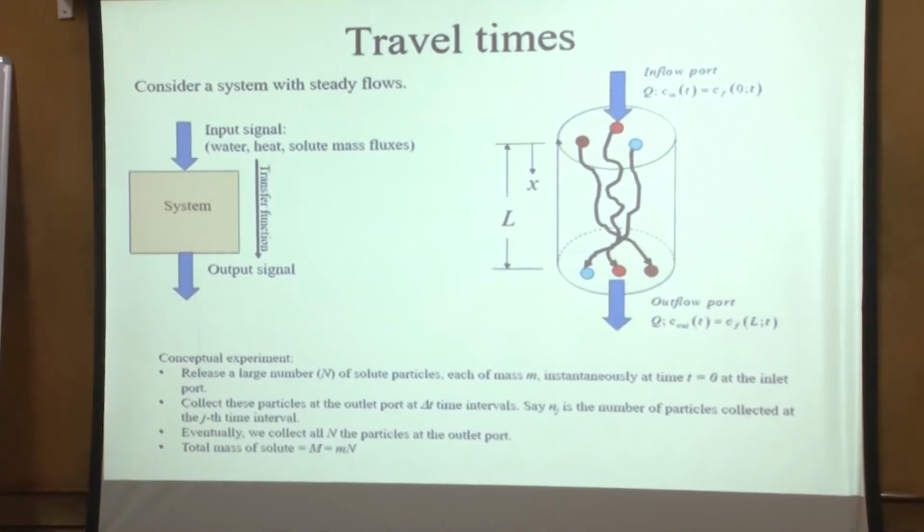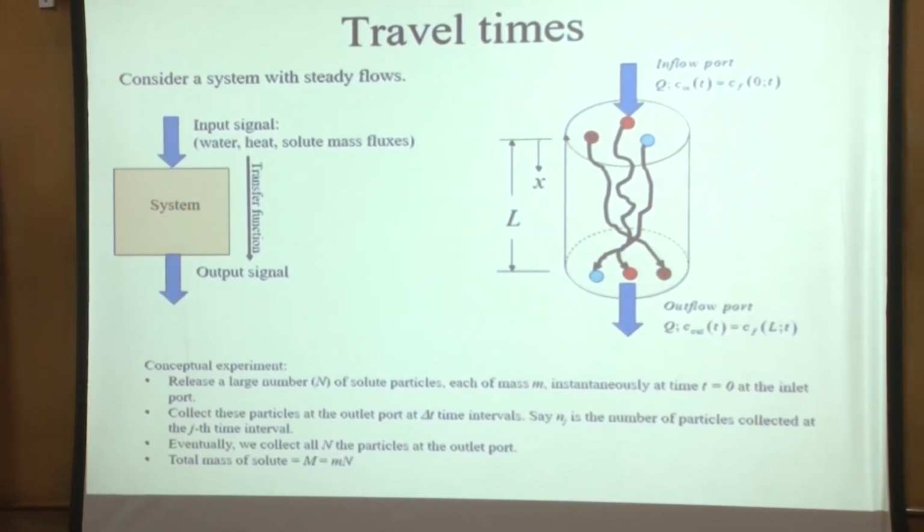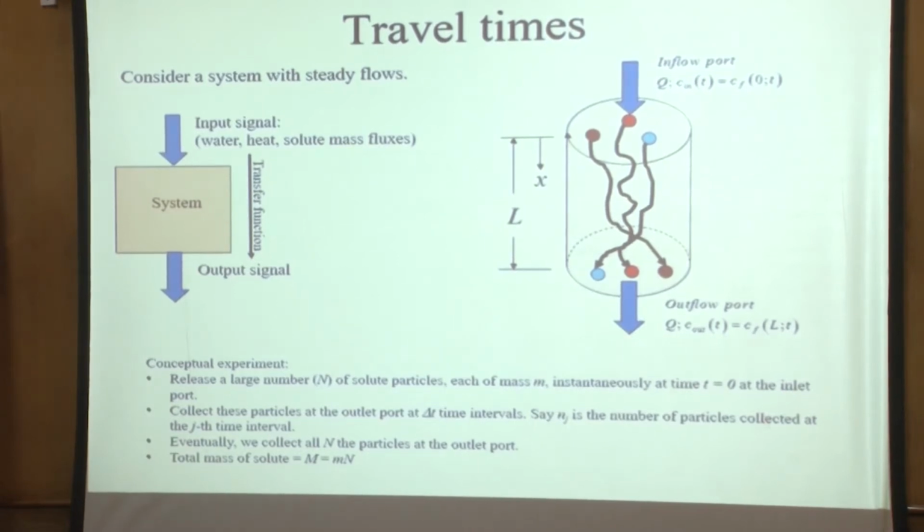And here I want to motivate our thinking in terms of linear systems theory. Much of what we do, whether it's solute transport, as long as the equations are linear, when you do unit hydrograph, when you do many other problems, we are essentially using linear system theory, which essentially says, I have a system, whatever input signal that I provide, whether it's water, heat, solute mass fluxes, and so on, the system is going to transfer it and I'll recover an output signal.